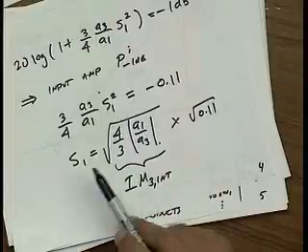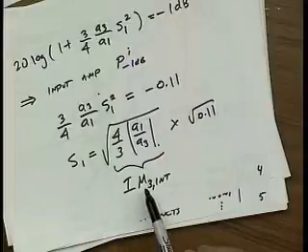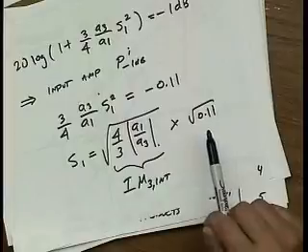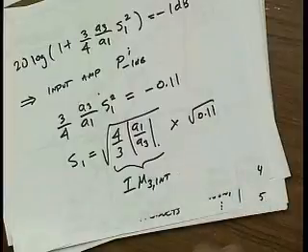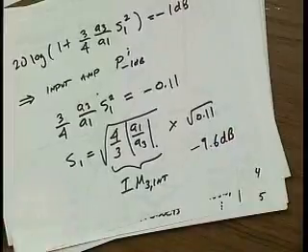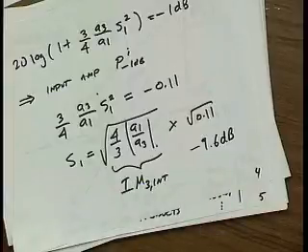And so you can see that the input 1 dB compression point is related to the intercept point by this factor of square root of 0.11. I believe that's 9.6 dB. So if you have a calculator, you can verify this. But this corresponds to backing off about 10 dB from the intercept point.